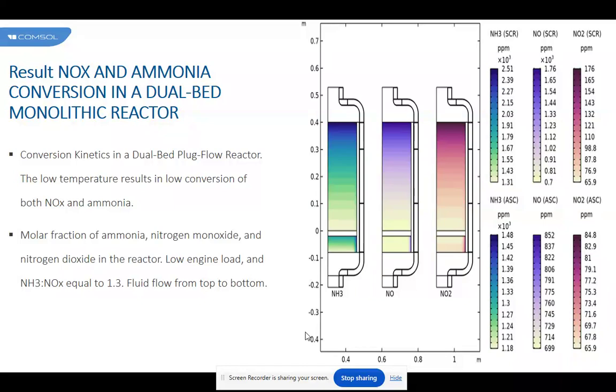The catalytic converter forms the basis of the automotive exhaust gas aftertreatment system used on most passenger vehicles in Europe, North America, and other regions to control emissions such as carbon monoxide, hydrocarbons, and oxides of nitrogen. Although the catalyst formulation varies depending on the mode of engine operation, the heart of the catalytic converter is a multi-channel honeycomb monolithic substrate, the walls of which are covered with the catalytic washcoat.